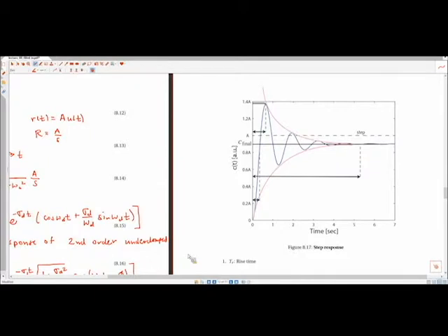We'll talk about other cases where it will not fall short, but for a mass spring damper system with proportional control, it's always going to fall short. So A is here, we react, oscillate, and then we fall short of A, right? Yes, proportional control. We'll talk about ways to improve upon this later. What this is telling us is that it did something resembling what we wanted it to do. It moved in the right direction, did some good things. It didn't quite do everything we wanted. But here's where we're going to start for this discussion in terms of trying to understand the response.